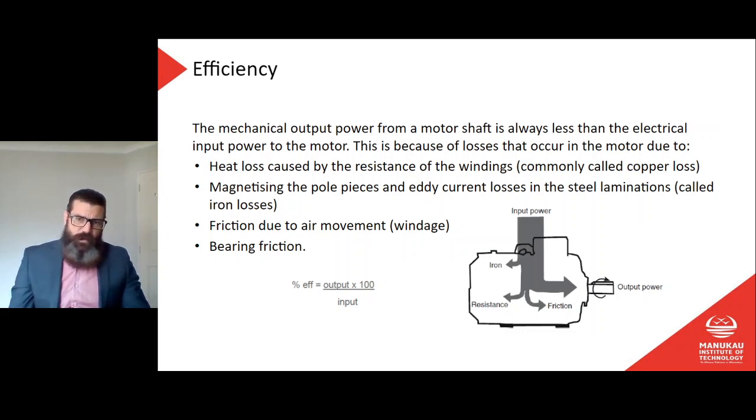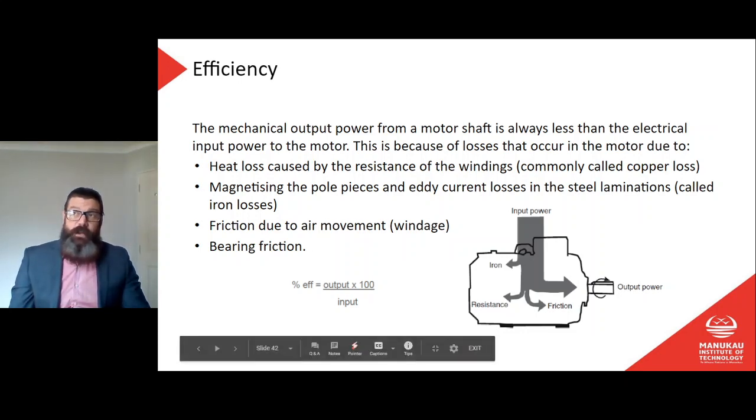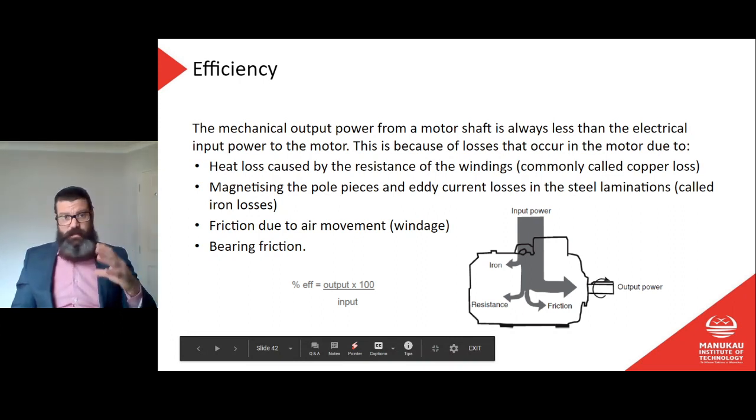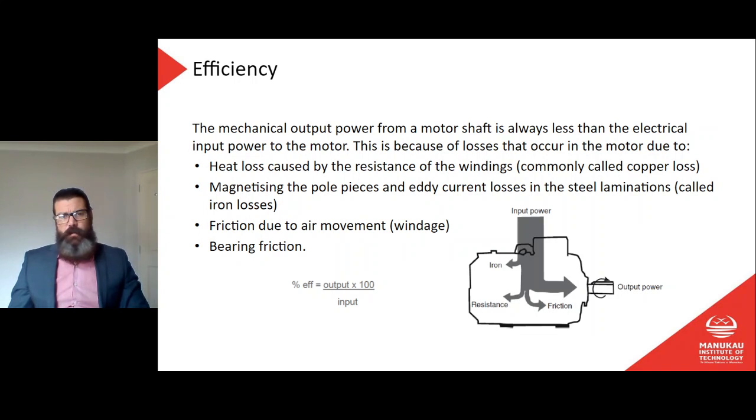Friction due to air movement, so windage, so just friction due to air movement of the rotor moving in air, but also remember we're going to probably have a fan attached to our motor shaft, so we're going to lose some of our motor power from that.